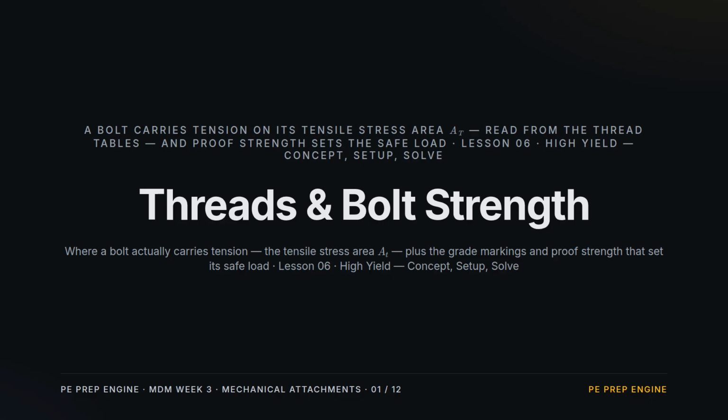This lesson does three things. It reads the tensile stress area off the handbook thread tables, decodes the grade and class markings that tell you how strong a bolt is, and finds the proof load, the largest tension a bolt takes with no permanent set. Two quick table lookups, one metric and one unified, that Lesson 8 will reuse for bolt torque.